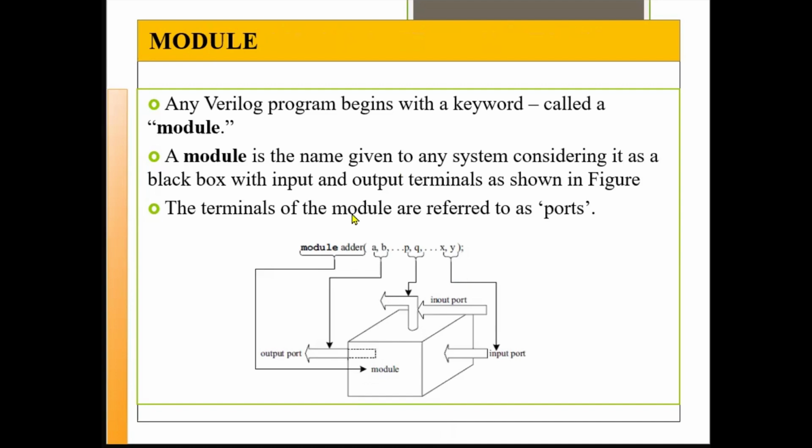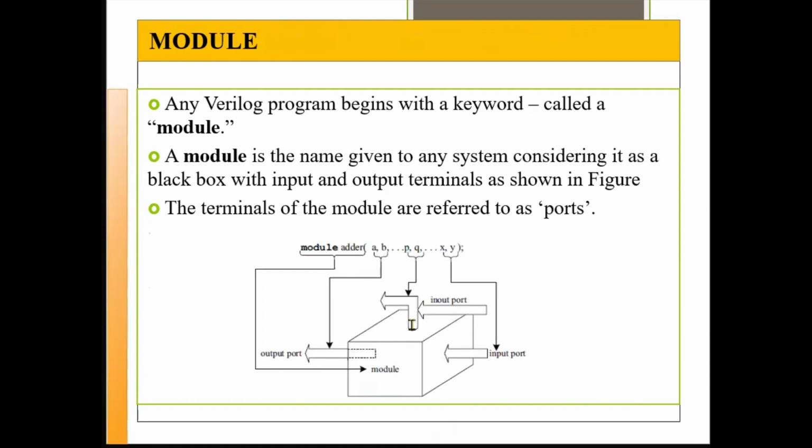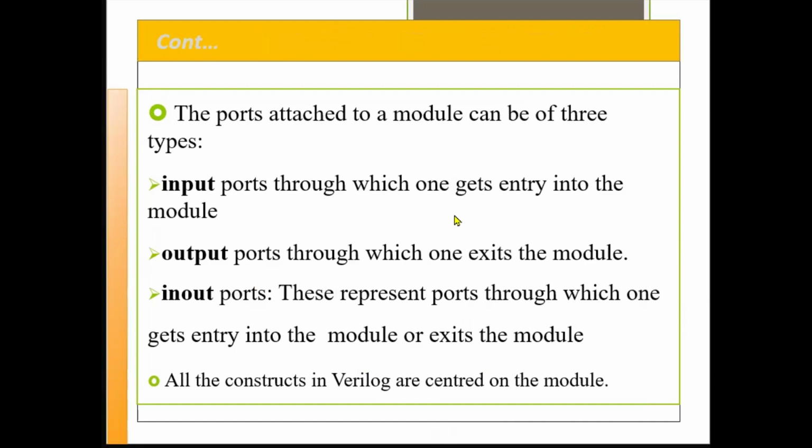When we are going to write a module, it has certain syntaxes. We have to follow those syntaxes. Verilog is case sensitive. All the keywords that we are going to use should be written in small letters. So here we are going to have the module, input ports, output ports, and how to declare a module. Let us see with an example.